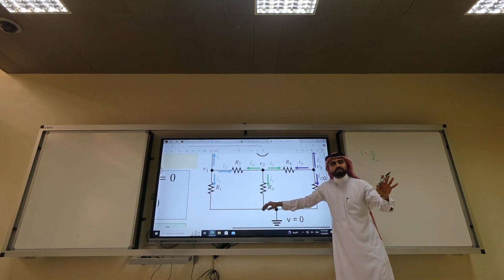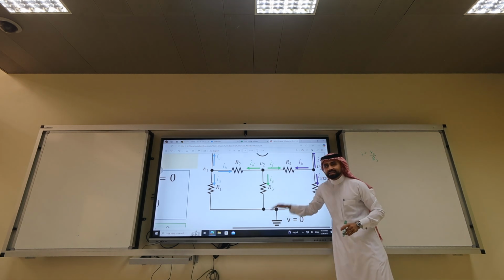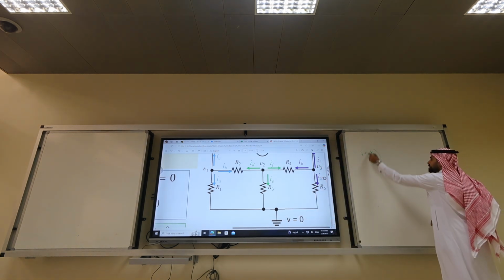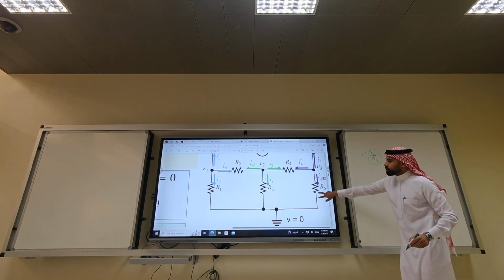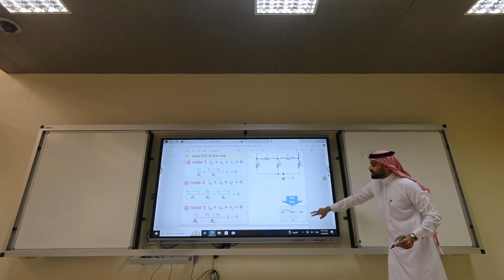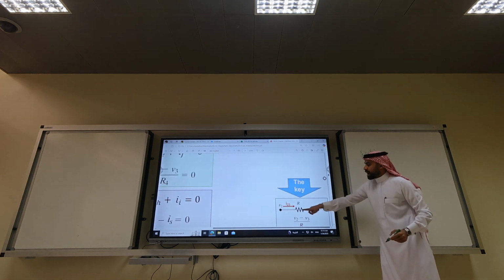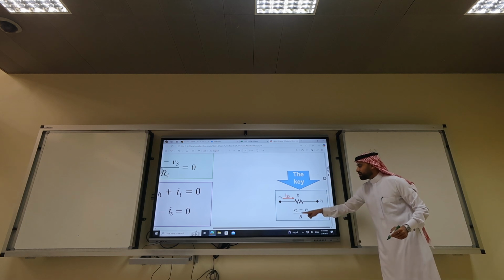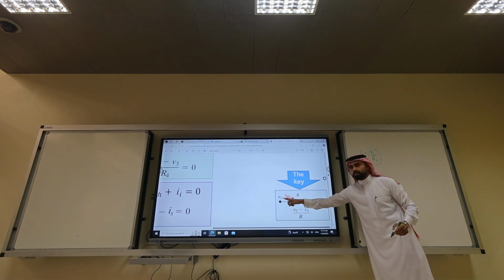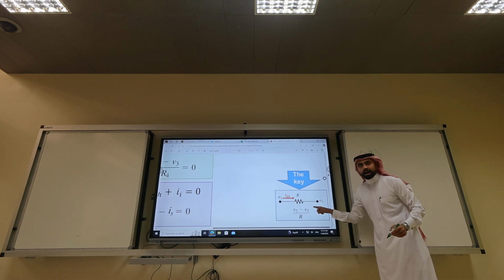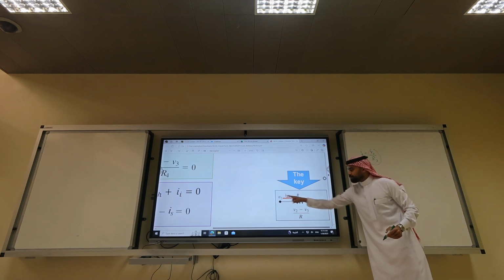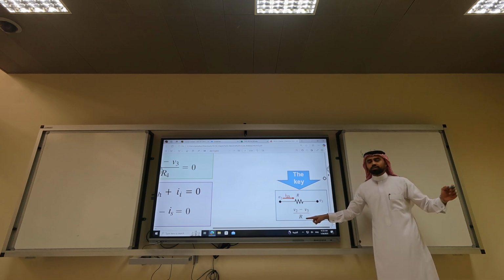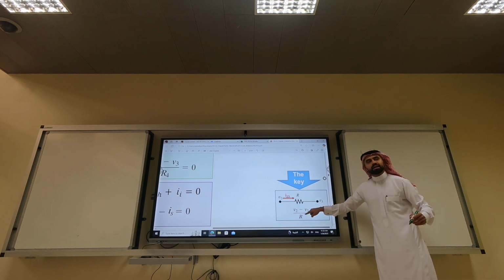So you select a reference voltage to make it 5 minus 0 so that you can apply the method. So this should be IE. In other words, the key element here: across any resistor R between nodes 2 and 3, the current from 2 to 3 is going to be V2 minus V3 over R. Why do we select a reference voltage? To eliminate this and make it 0.